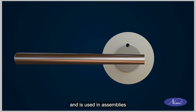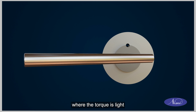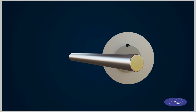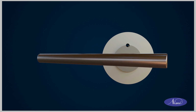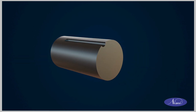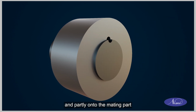Round key. It is of cylindrical cross-section and is used in assemblies to secure the mating components where the torque is light. The key is fitted parallel to the shaft into the drilled hole made partly onto the shaft and partly onto the mating part.